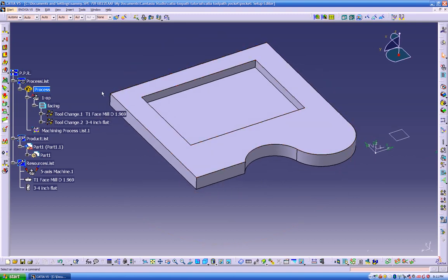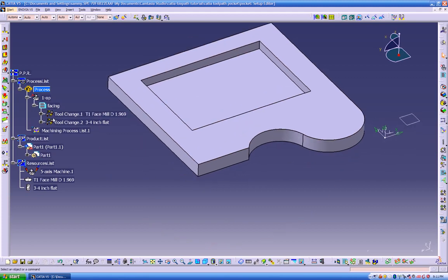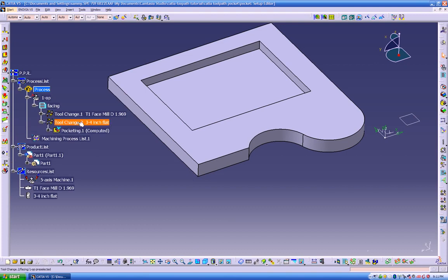First I'm going to machine this edge, and then this edge in here. Assuming we have two clamps to hold the part over here, then we're going to stop the program, swap the clamps and machine the leftovers. So let's make another contouring operation with this 3/4 inch flat.